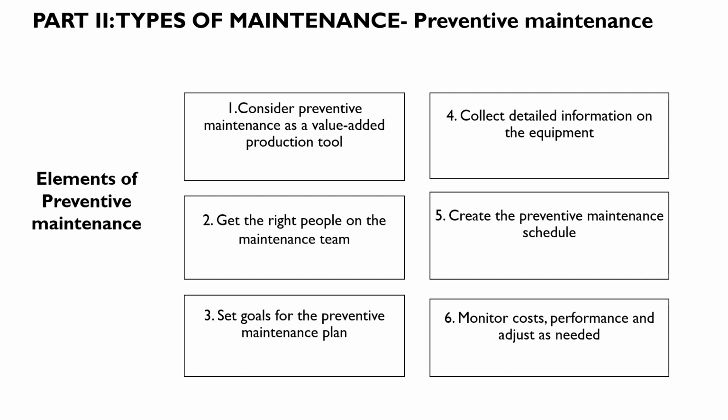5. Create the preventive maintenance schedule, based on prior equipment maintenance history, maintenance standards for individual assets, inspection times, technician availability, equipment location, and production downtime. Keeping these factors in mind ensures optimal maintenance with minimal operation disruption.